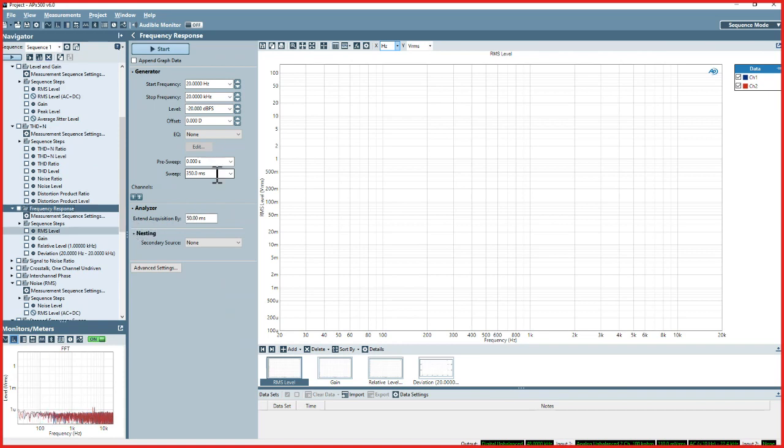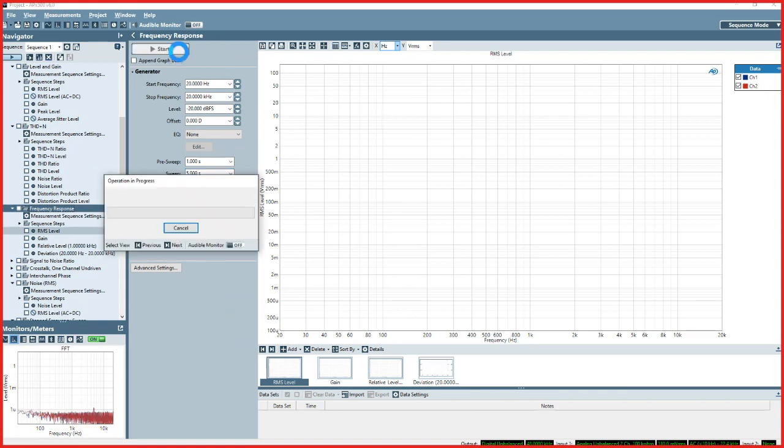We can look at the frequency response of the device. So there are a few different takes on this, whether frequency response should be run at full scale or below full scale. And the issue there is if the device has some positive frequency response excursions, you may drive it into clipping. So I'll say that typically frequency response is measured well below full scale.